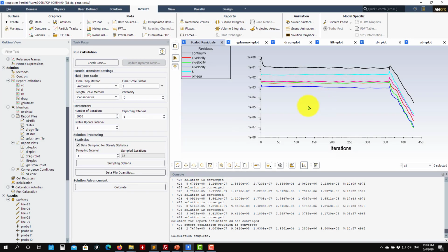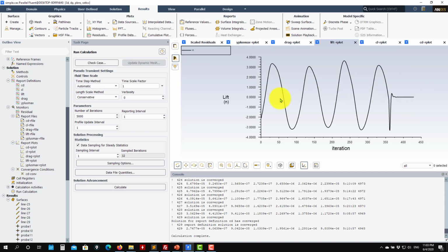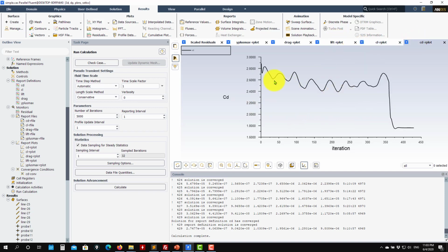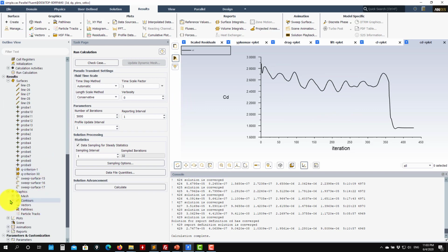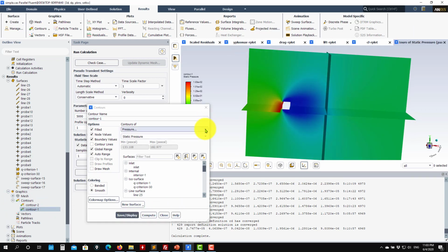Okay, so look at the behavior of the coupled solver. See that very fast it went to the steady solution, okay? And CL and CD stabilize, kind of stabilize about the mean value of the sample, okay? Not necessarily, but it looks like. For instance, here it's quite different. So if we check here the RL, okay, we have pressure.